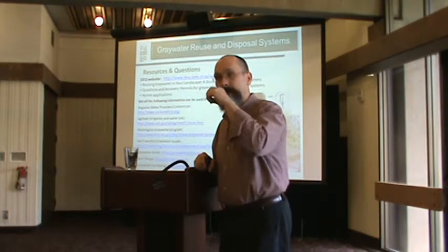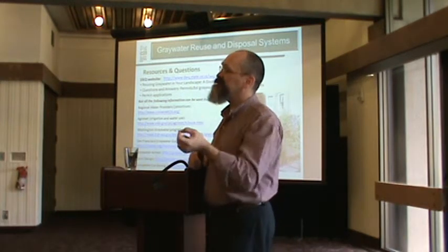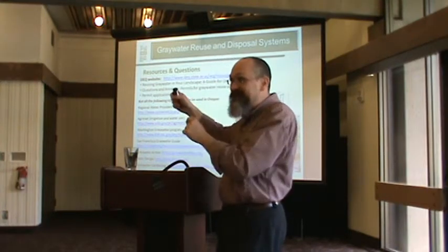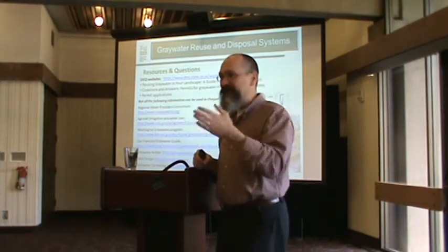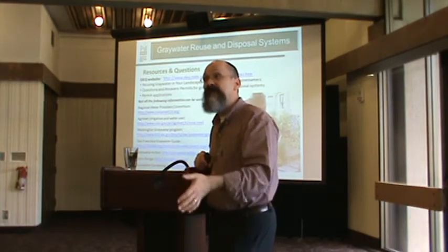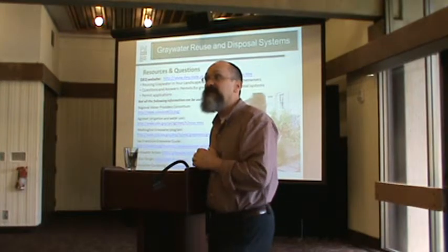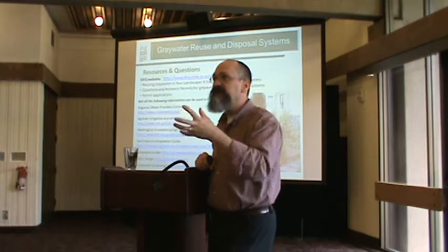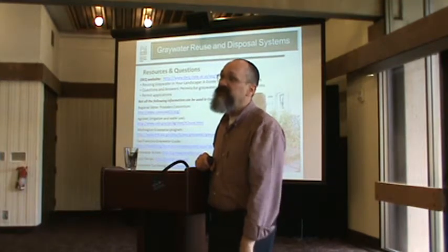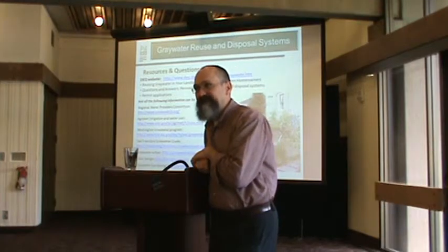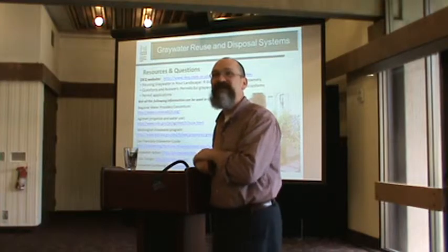But if you cut into it outside the house, this was a discussion I had with the state building codes, and part of what they're supposed to be doing is getting out to the local building officials who has jurisdiction on these things. But everything up to and including that diversion device is subject to plumbing code, because that diversion device is a health and safety issue, so it needs to meet plumbing code. So even if it's outside of the house, they're supposed to be looking at it.